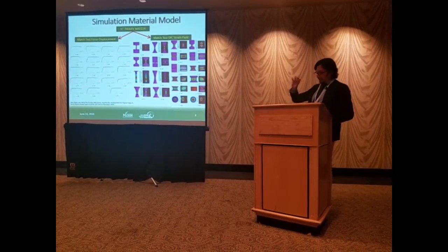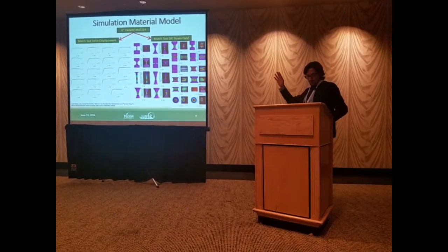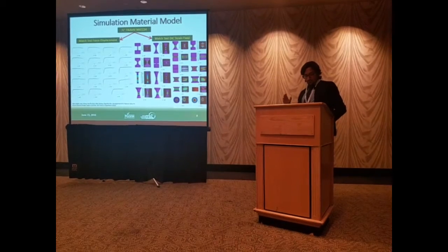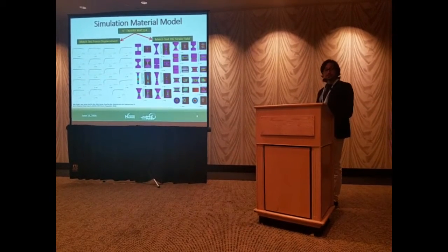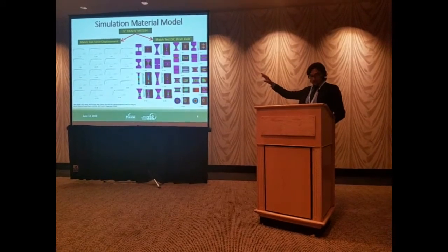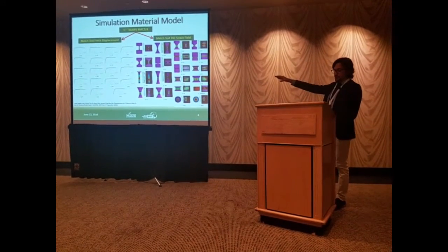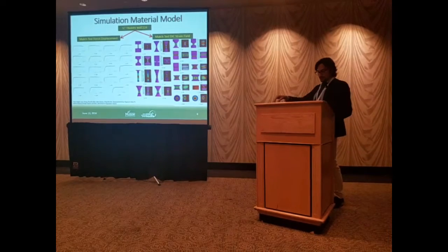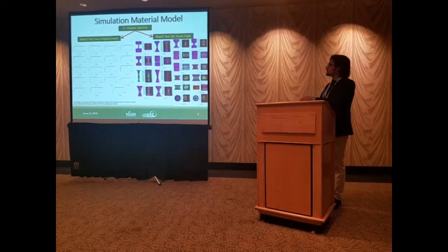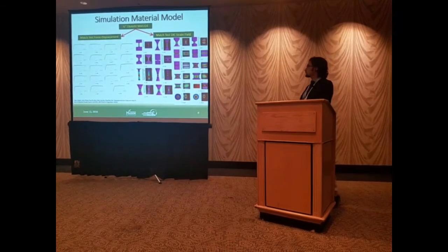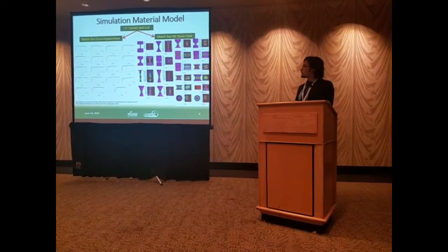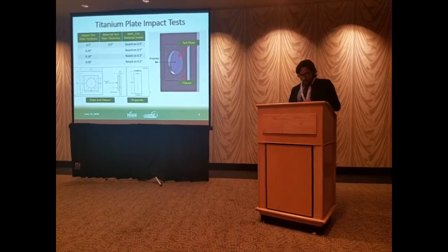So, starting from the material test, we develop all the input curves to achieve a single MAT224 material model that is able to match all the force versus displacement and also the DIC image for each type of test. And so these are the results. Here we have a tension test, punch test, compression test, and torsion test.